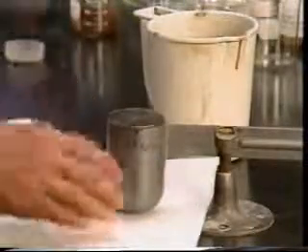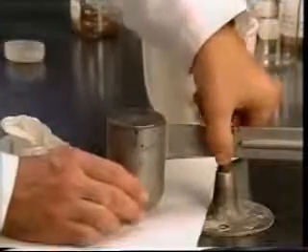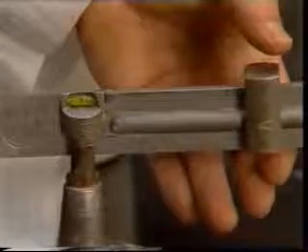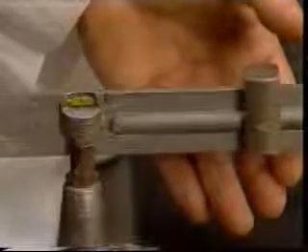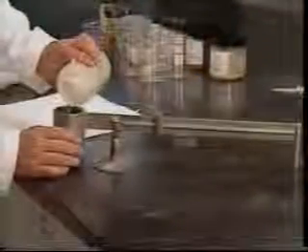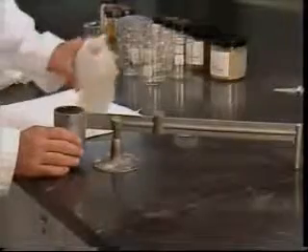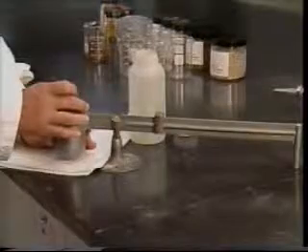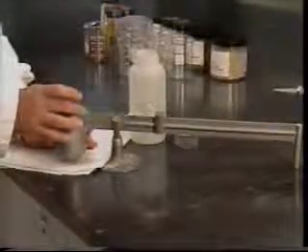With a finger over the vent hole, the balance is washed and wiped clean, and then placed with a knife edge on the fulcrum rest. The counterbalance is adjusted until the spirit level bubble is on the center line. With the balance steady, the mud weight may be read at the edge of the counterbalance nearest the fulcrum. After noting the reading, the balance is emptied, cleaned, and dried. This instrument may be calibrated by checking the density of clean fresh water. If in error, it may be adjusted by adding or removing lead shot at the end of the arm.